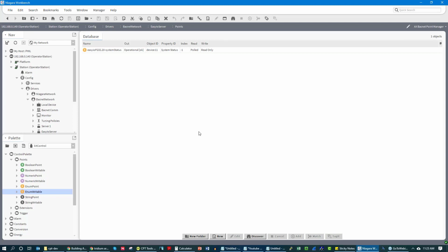We often have to use a second set of software known as programming software to actually go and program the field controllers. And it's at this point that a controls engineer or controls technician would discover these points and would start to say, okay, the spec says I need to trend X points for X amount of time, or I need to have alarms on them, or I need to have schedules, and they would start to set that up.